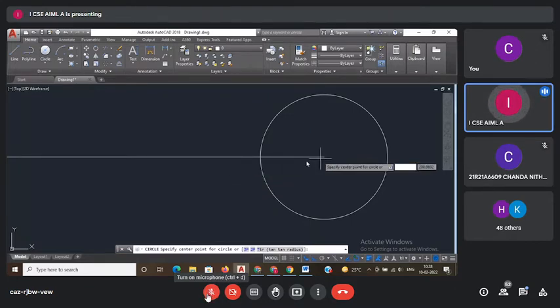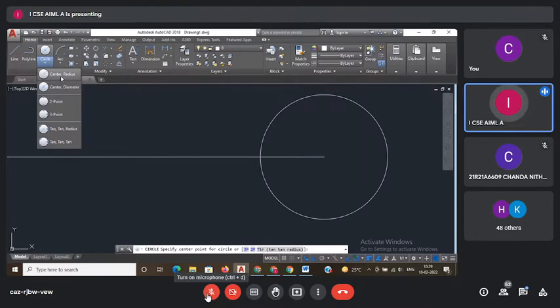Here I know the center of the larger circle. On this larger circle, the smaller circle is rolling. For that smaller circle, I don't know the center. I just drew a rough line. Okay, it's not center and diameter, it's not center and radius. You have to select the 2-point method.